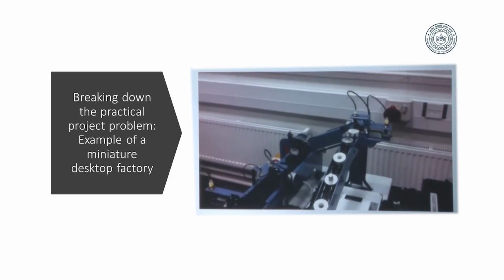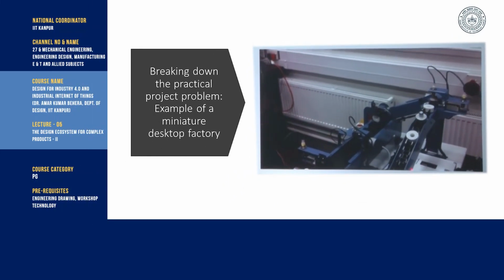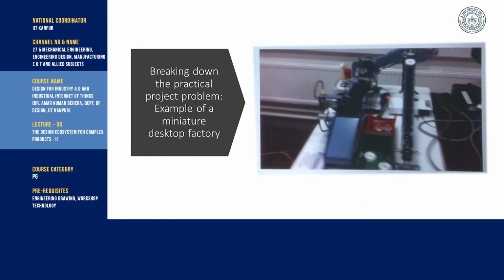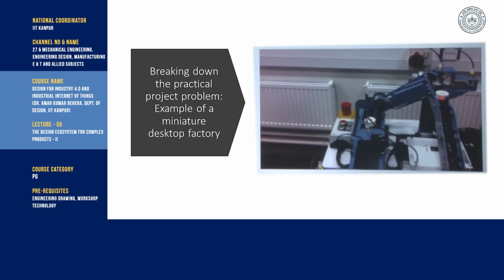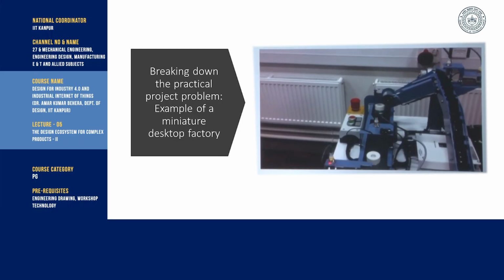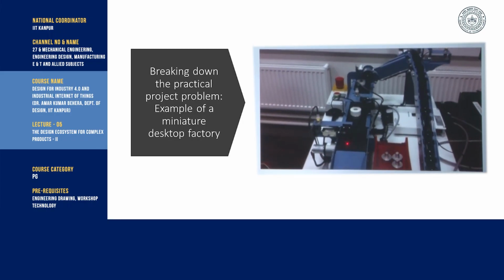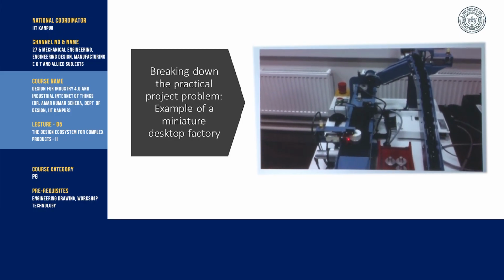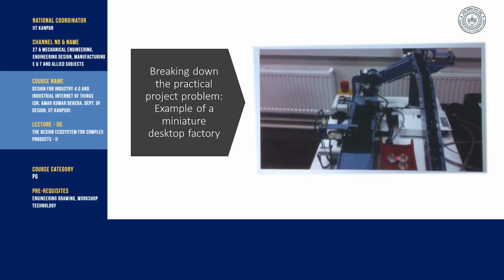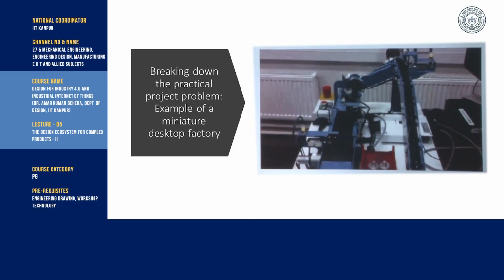What you can see here is there is a channel through which these are going up a conveyor belt and they are coming down, and there are some sensors. You can see these sensors glowing, and this is a red box. If the assembly does not take place, then there is a unit here which will kick them into this box. If the assembly is correct, there is a sensor here which detects whether the assembly is correct or not, and then it lets them through.